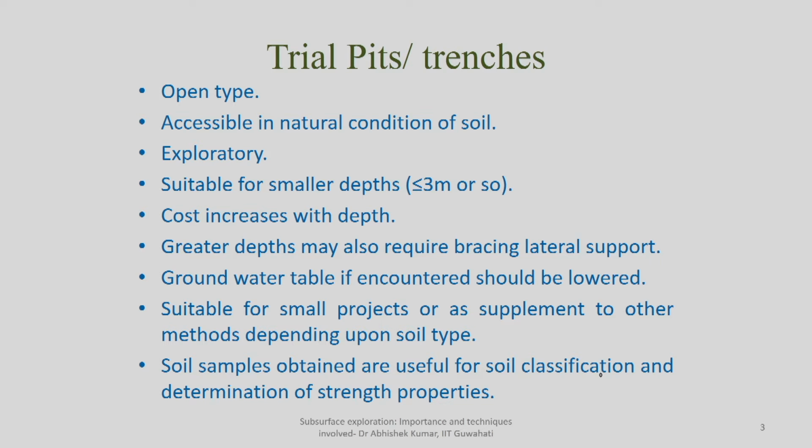The only disadvantage here is that such kinds of investigation are selected for shallower depth, 3 meters or so, because you are actually not doing any test at the site, you are basically collecting the sample. So, even if you go for soil classification or strength determination, you have to have detailed investigation or detailed tests to be conducted in the laboratory.